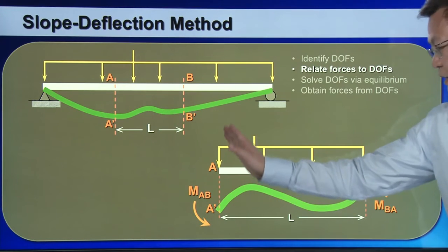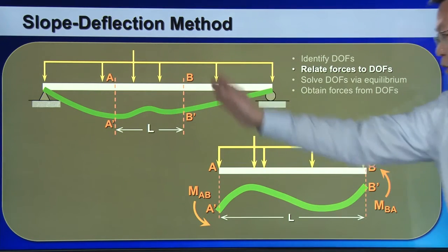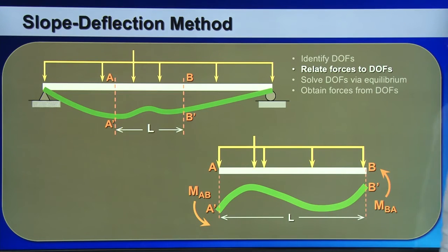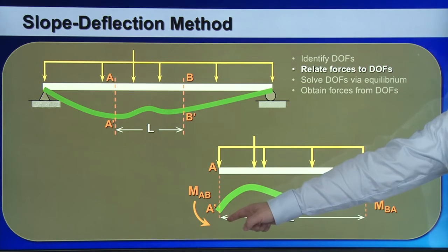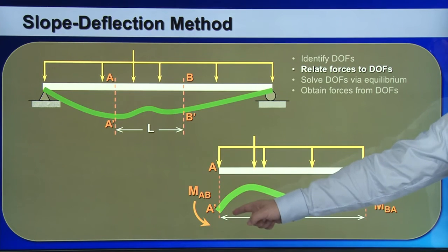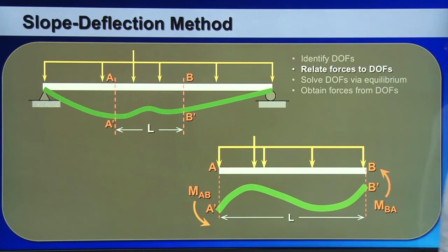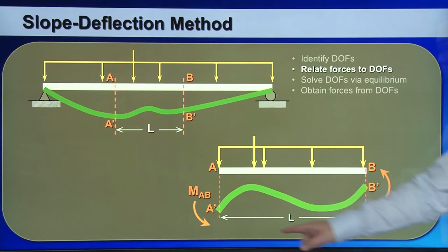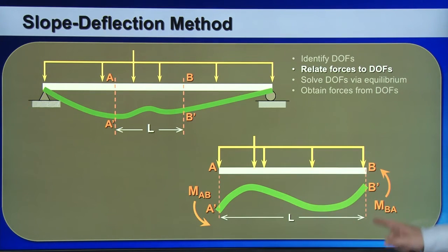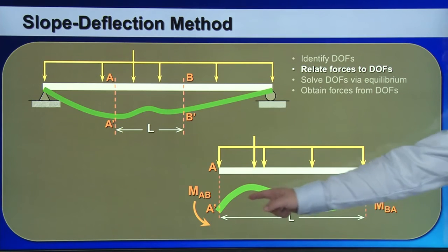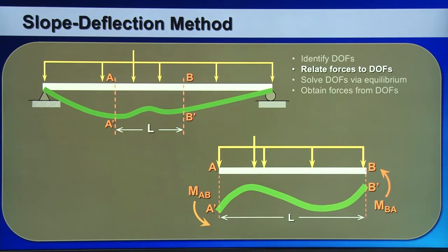At the two cross-sections A and B, there will be internal forces, including bending moments as well as shear forces. But if you know the bending moment, you can calculate the shear forces through local equilibrium. So let me temporarily neglect the shear forces. Just keep the bending moment acting on this segment.